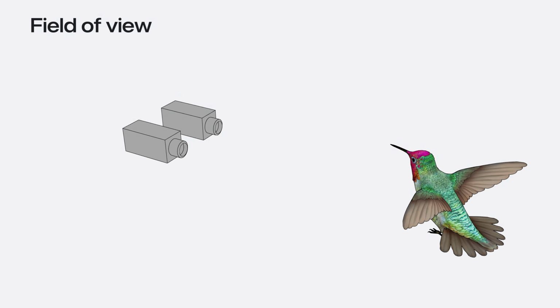The next piece of metadata, the field of view, is the horizontal angle in degrees captured by each camera. Generally, the higher the field of view, the more immersive, since more of the scene is in view. However, for a fixed sensor, higher fields of view will spread more content across the same number of pixels, so the angular resolution will be lower. Additionally, since our projection is rectilinear, fields of view greater than 90 degrees will be inefficient in their angular sampling densities, especially on the edges, and thus aren't really recommended. For this example, I'm going to use 60 degrees for the field of view.